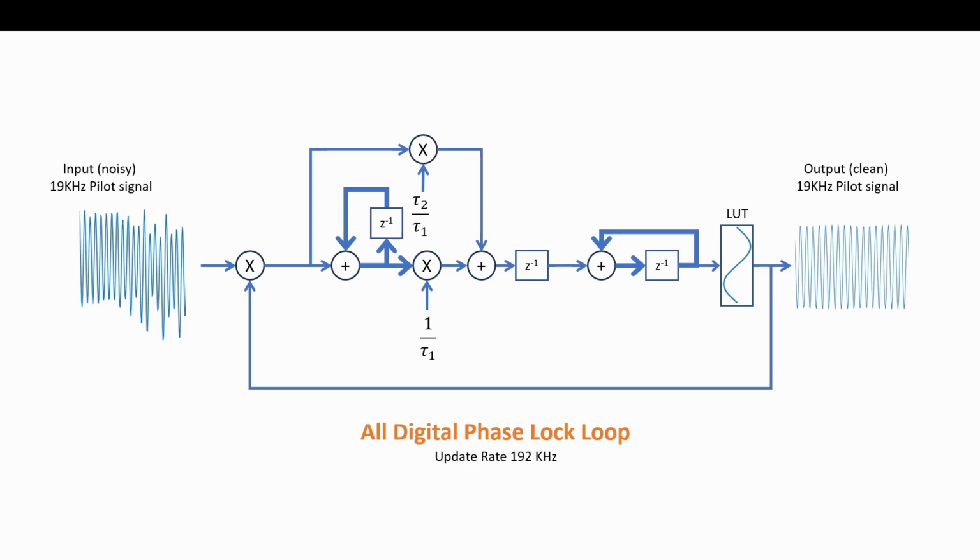Imagine if I put in just a digital value of 1, and this is a counter, an accumulator. It would grow on each clock cycle by 1. And imagine I took just the MSBs of that, so this can have very high precision. Eventually, we will count through that lookup table, which will generate the sine wave at the output.